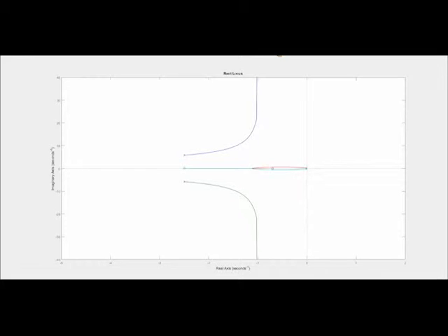The simplest way to look at it is proportional gain. And that's often what we'll do: we'll say we have some dynamics in our controller, and let's just look at how the gain affects the system. That would say that basically the proportional, integral, and derivative gains are all changing by some amount, and they have their own different weights, but we're changing some parameter that changes them all by the same factor.